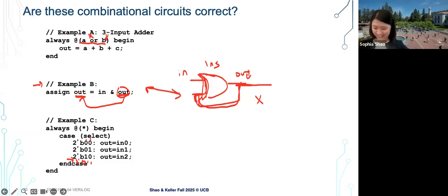Verilog is a very flexible language, right? We'll talk later about constructs that are not synthesizable, that are only used for simulation, and you can write those down. And there's an awful lot of stuff you can write down that the tool will do its best to synthesize, but you really ought not to. So what we're showing you here is staying on the path: a few very specifically defined things that, if you do them, give good results. If you stray off the path, it might still work, but it's probably not doing what you want.